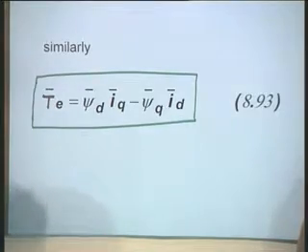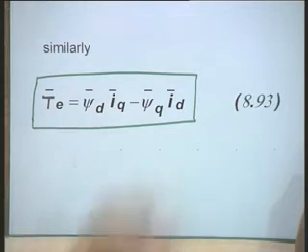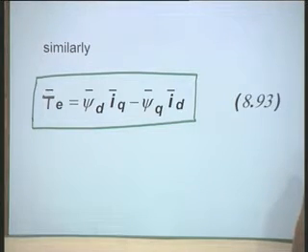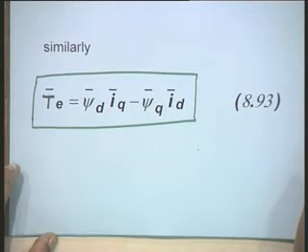Other stator circuit and rotor circuit equations are also equally important, right? Because that gives the complete model. We have to write down the stator circuit equations, rotor circuit equations, stator circuit flux linkages, rotor circuit flux linkages, and all these things have to be written in per unit by establishing proper per unit bases. But when I say that the per unit air gap torque is given by this expression, this is quite important. Can you tell me why?